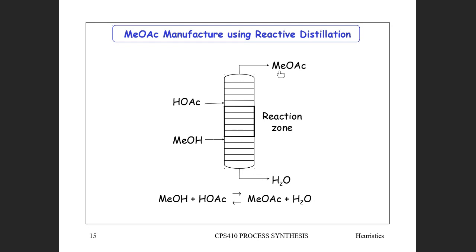Then you've got to increase the temperature, the pressure of your distillation column, so that you get an average, because the temperature in this reaction zone is dependent on the boiling point of these components. So you would need to design the distillation column to operate at a suitable pressure, so that the temperature in the reaction zone is suitable for the catalyst. And so that restricts things a little bit, and therefore there's only a limited number of components that would be suitable to operate at the typical temperatures that catalytic reactors operate at.